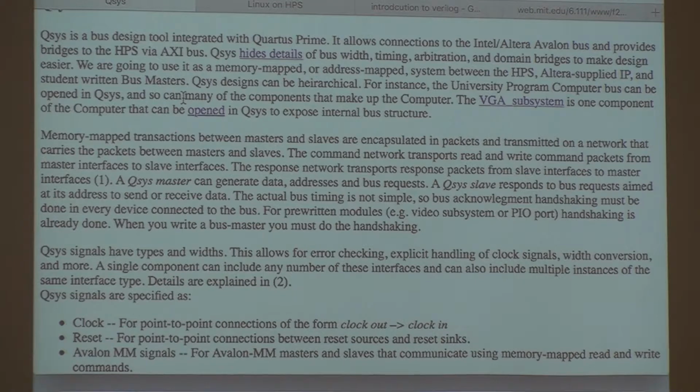On the left-hand side of Qsys, there's a box that says, don't use this module. You click it, it leaves all the connections there, so you don't have to reconnect it, it just disables it. And what you should do is just go down, click, click, click, turn off everything on that bus, except maybe the LEDs, and then write a program on the HPS that talks to the LEDs and blinks the LEDs once a second.